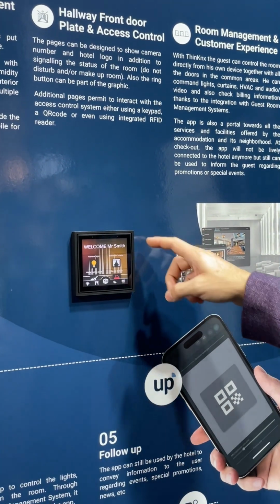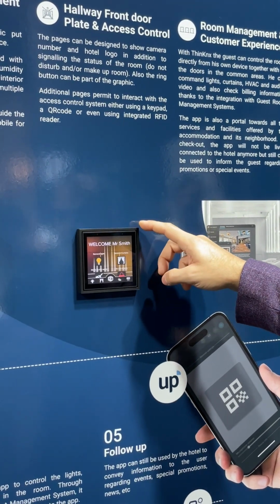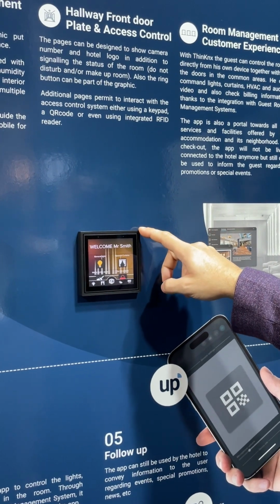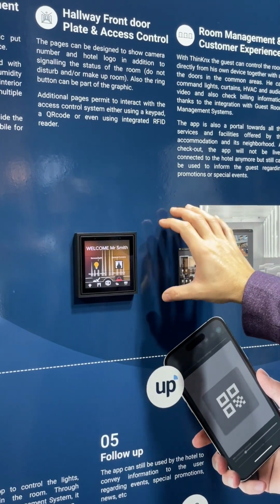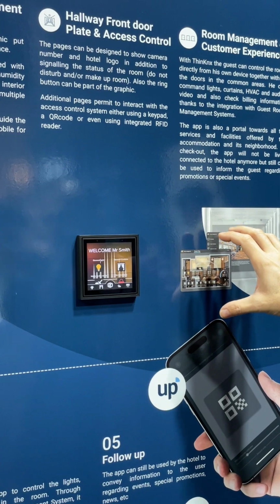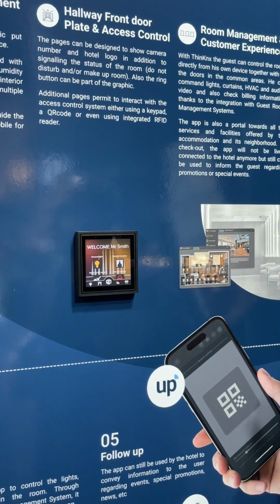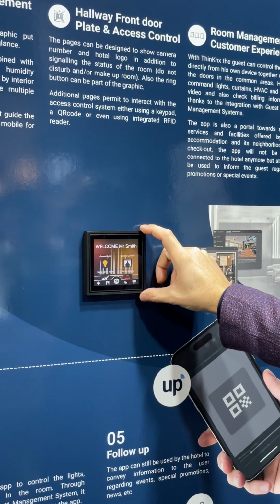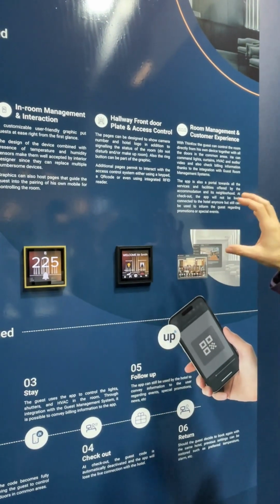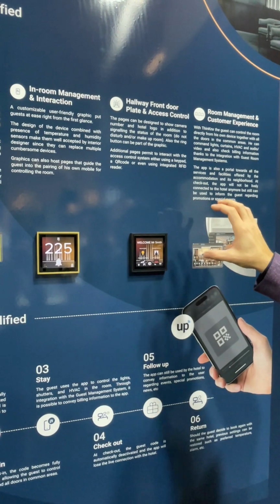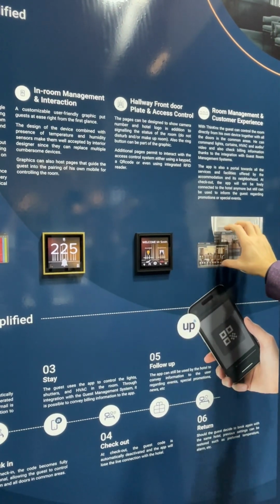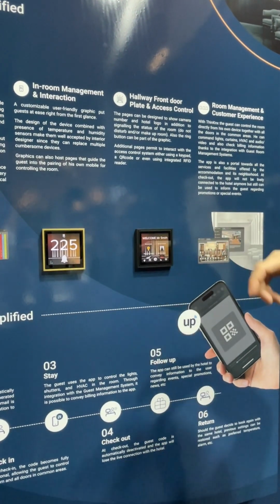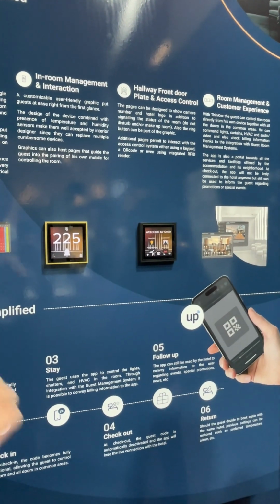And also this thing is very powerful because since it comes with the KNX IP interface, you can also imagine that if you want to keep each room separated in terms of KNX bus, you can use it as a KNX router. So you can have each room with its own power supply, actuator, and so on, in order to have, let's say, still overall control of the room.